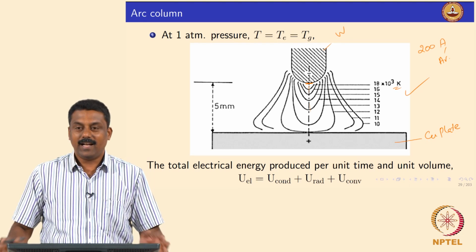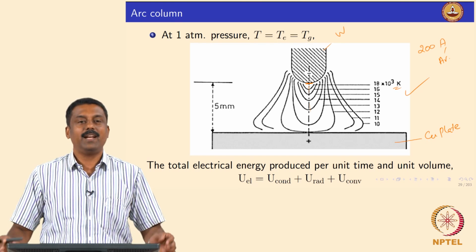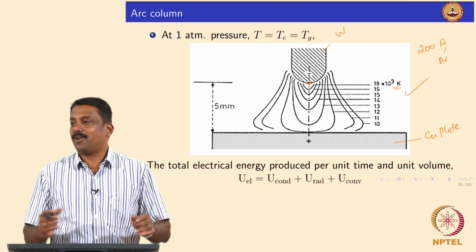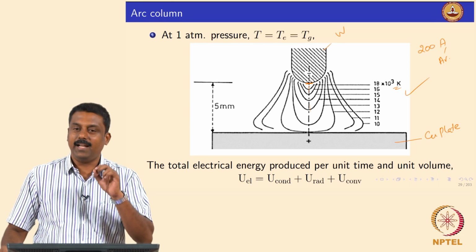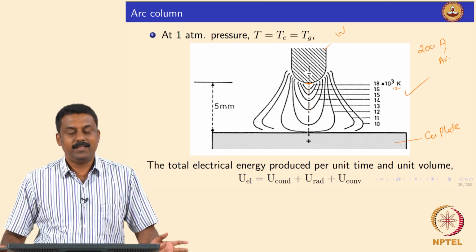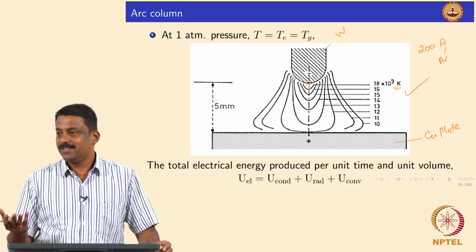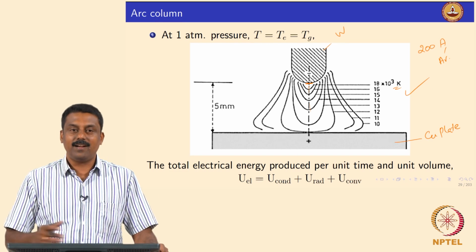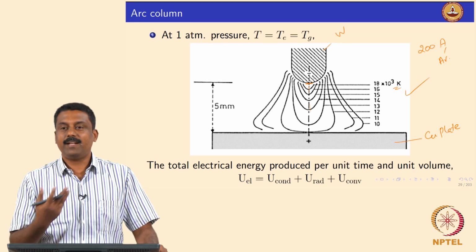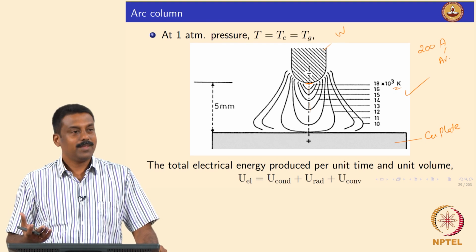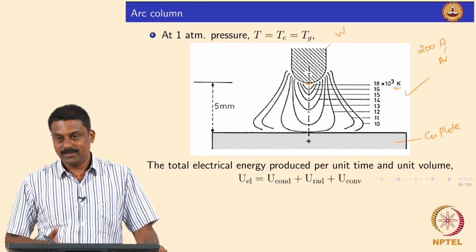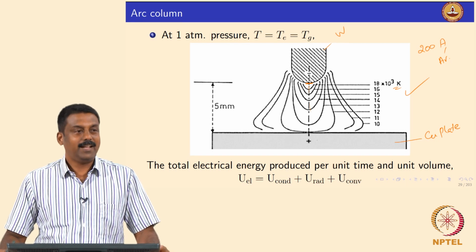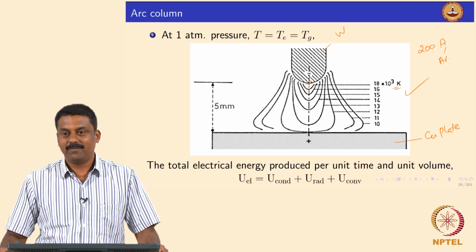Electrons carry more heat than ions, so the heat is carried away by electrons very effectively from the tip, which is already very tiny, 10 power minus 8. So you don't melt because of the effective conduction, and because the electrons are not reaching the electrode. The heat is effectively transferred by the electrons towards the anode in this case. So the anode is molten, because the electrons are reaching the anode, which carry the heat.